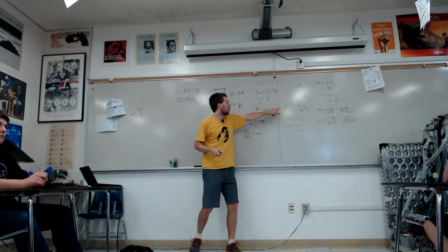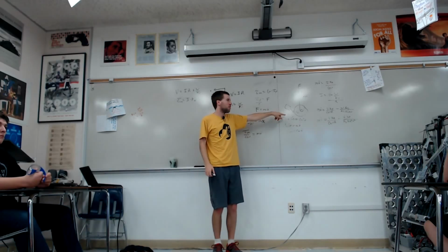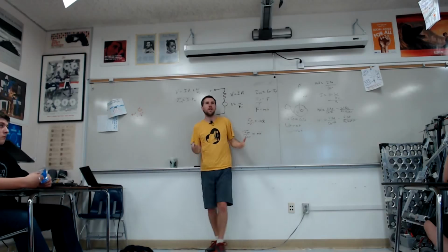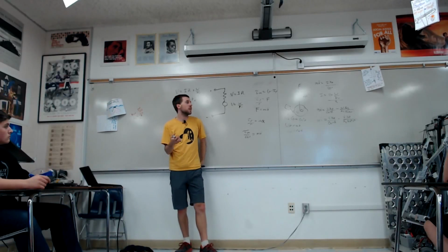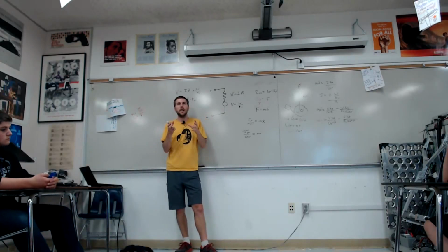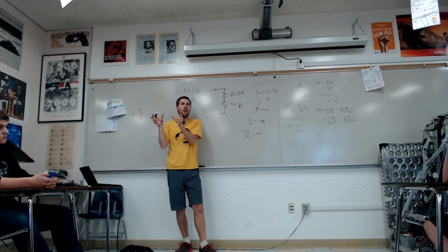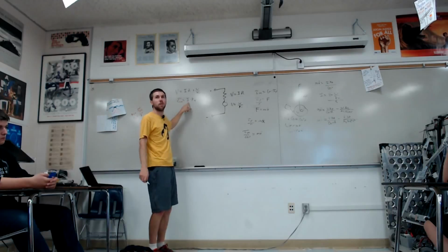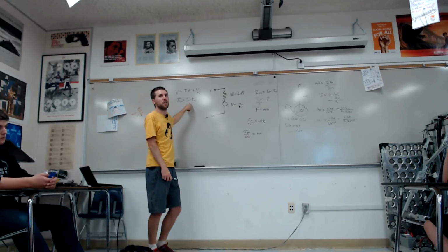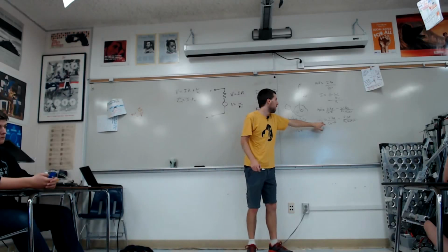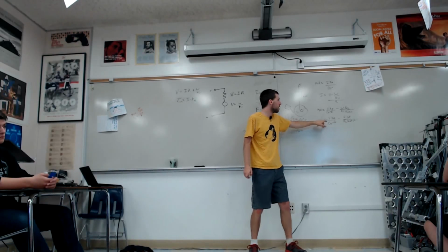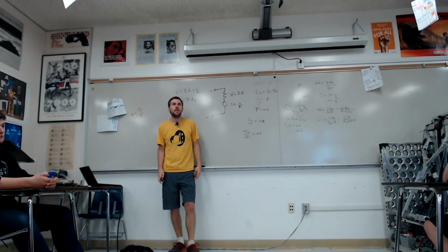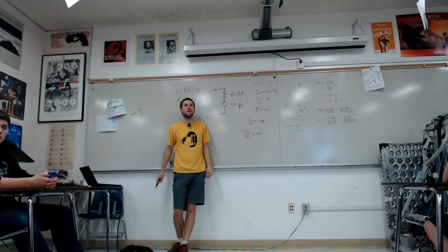So we're going to put a voltage in, and I don't really care where my motor is. I care where my mass is. I care where the box is. Depending on the year, I care where whatever we're manipulating is. So we want to get all of our physics to take a voltage in and talk about position, velocity, acceleration of the output. Here we're starting with our motor, which is awesome. We now have a motor model, but this doesn't tell us what our output's doing. So we have to work through the physics to get the acceleration of our carriage, given the voltage and the velocity. Now that's actually something useful that we can simulate. That was a good question, thank you.